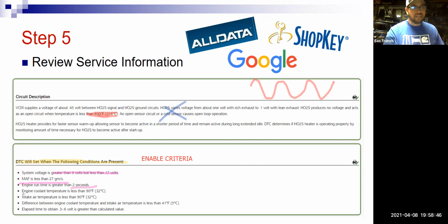Oh, coolant temperature is less than 90 degrees Fahrenheit. Remember that R code set and we were at 86 degrees. So remember, this is where I said it's going to need to see a cold engine, right? That's what it's telling us right there.